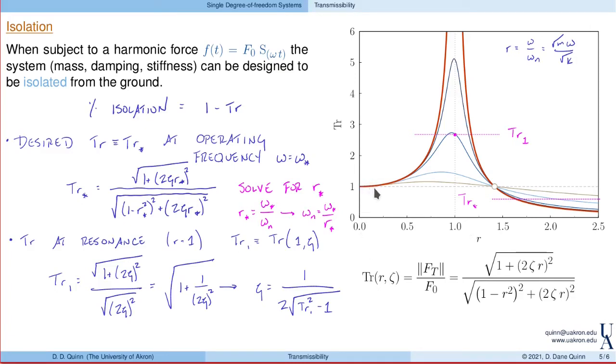So as we bring our system up to operating conditions, we actually would traverse this whole region of R. And you can kind of see what might happen. As our rotating speed passes through resonance, we can actually have a fairly large transmissibility. And as a result, we can have large vibrations being imposed to the supporting structure for our machine. Again, this transmissibility could be high. Part of our design goal is to keep that transmissibility limited as we pass through resonance.